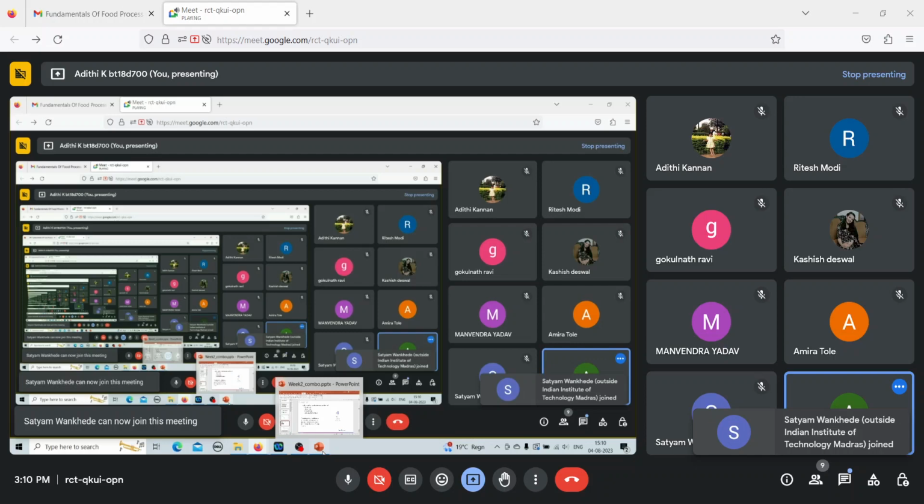So basically one of the parts will be rotating, and these rotational viscometers can be used for both Newtonian and non-Newtonian fluids, especially the shear thinning kinds. Because this is a very small region in between, a shear thinning fluid is much more preferable, because the more and more shear you give, the viscosity will decrease, so it will be easier to rotate.